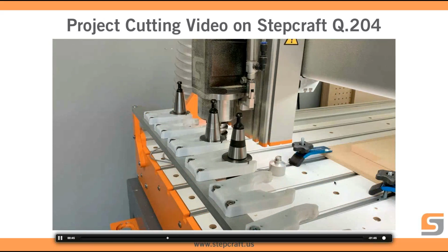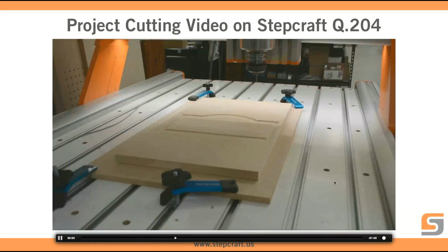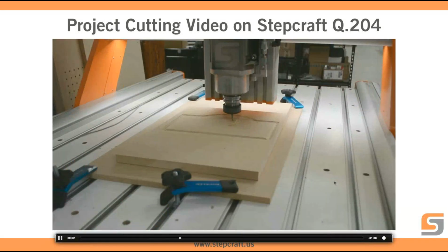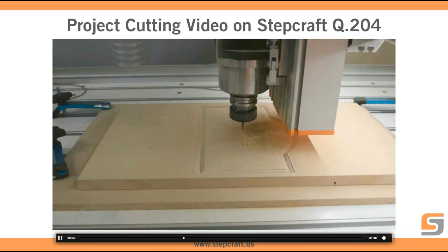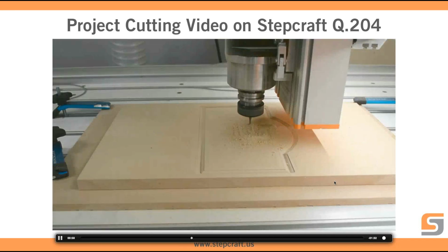So now we're grabbing tool number 2, which is our 1/8 inch end mill, and we're going to go over and pocket out the logo. Thankfully, when Dylan shot this video, he did speed everything up. Otherwise, we'd be sitting here for 20 minutes watching this run.